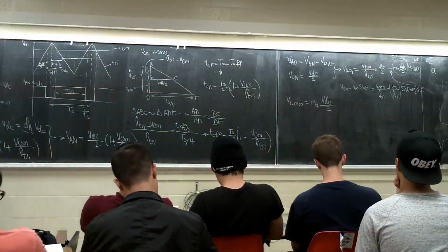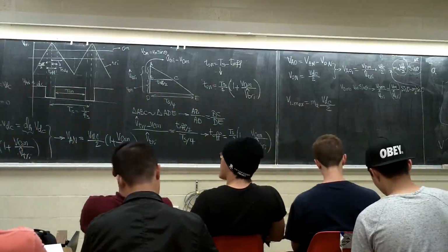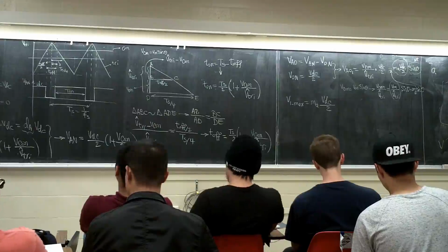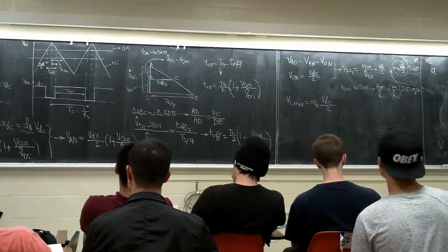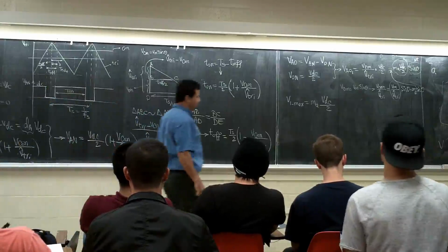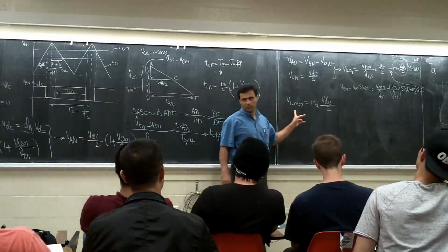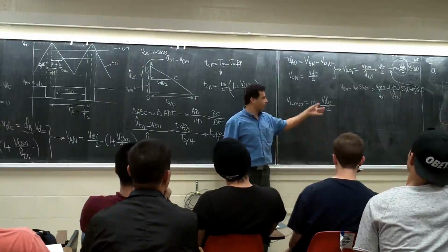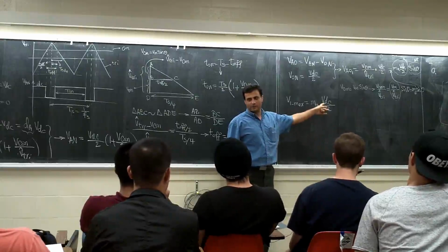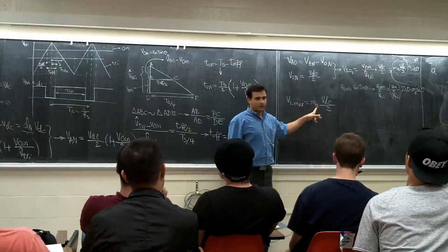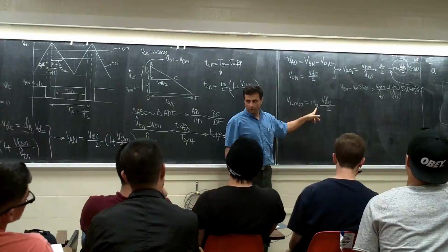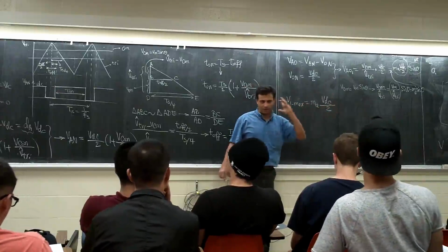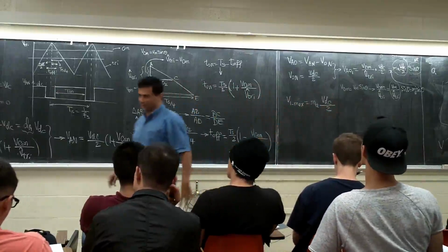Now if somebody tells you, hey, I want to have a sine PWM inverter with MA 0.8 to use at my home for my computer, how much battery should I put there? At home, how much do you need? 110 times the square root of 2, right? That's what you need. How much did he say I'm going to use MA? 0.8. You put it here and calculate VDC. We talked about this one. If MA is less than 1, we call it linear modulation. If you go more than 1, they call it non-linear modulation. We'll talk about that one in three phases, I'll go through the graph for that one.